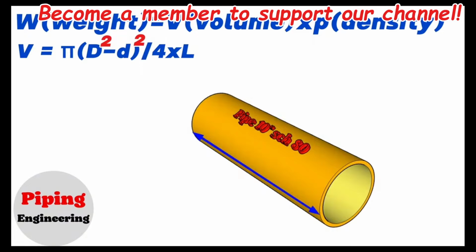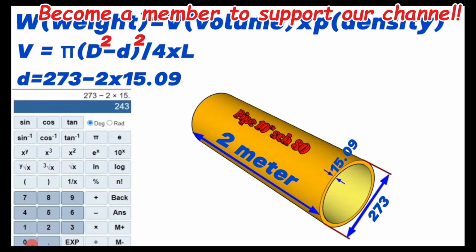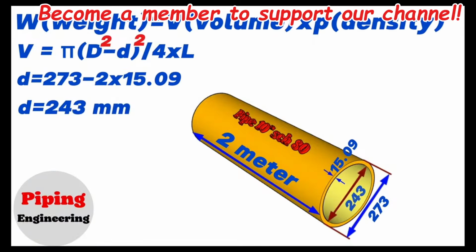The inside diameter will equal the outside diameter 273 minus 2 times the wall thickness 15.09. Using the calculator, we find that 273 minus 2 times 15.09 equals approximately 243. So, we calculated and found that the inside diameter of the 10-inch schedule 80 pipe in our example will equal 243 millimeters.